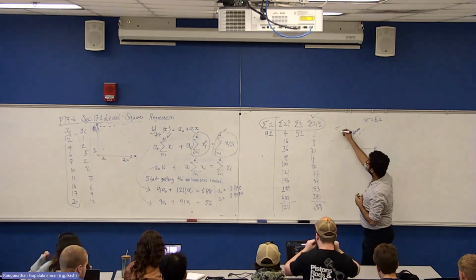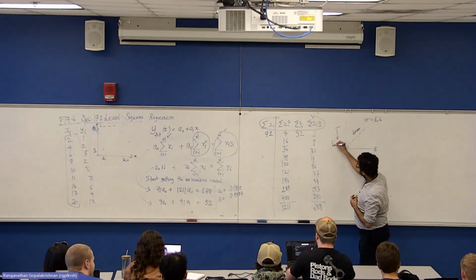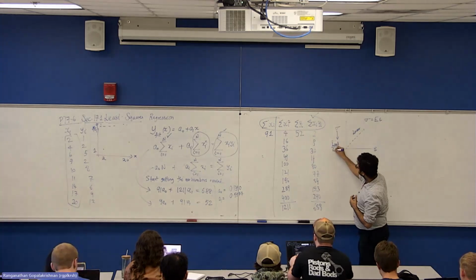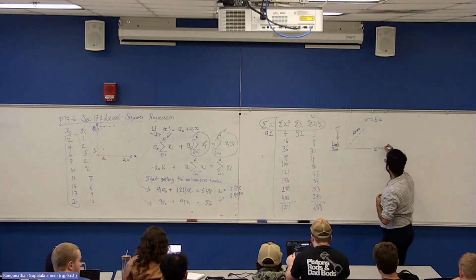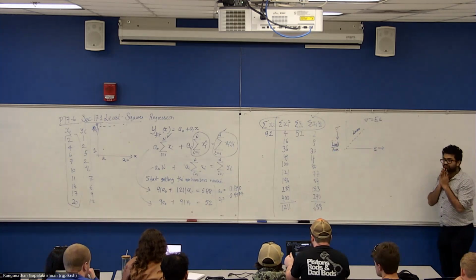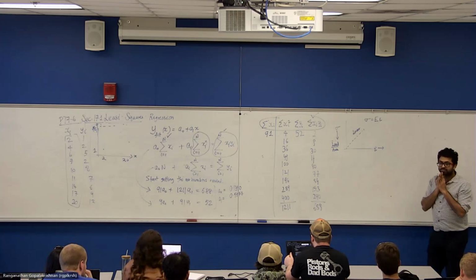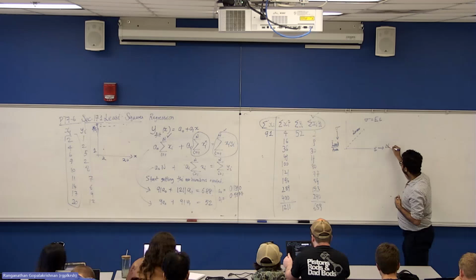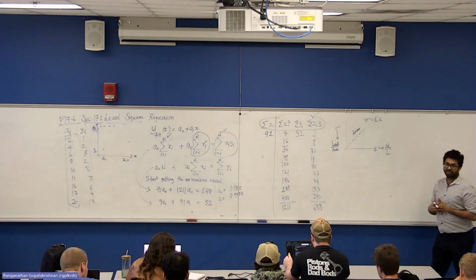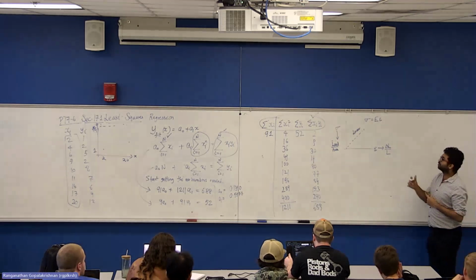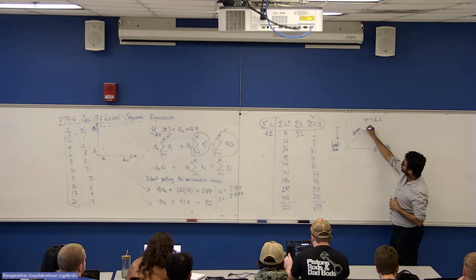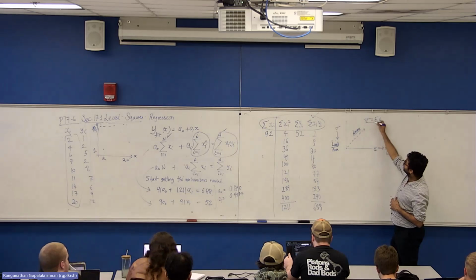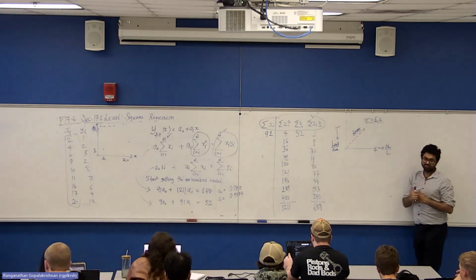Stress is measured as load per area. And the marker for strain is extension, delta L divided by L. You will see if there is a linear relation between them. If they are linear, then you know it's in the elastic region.